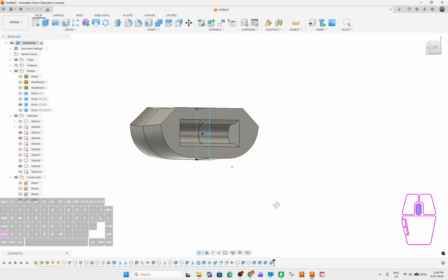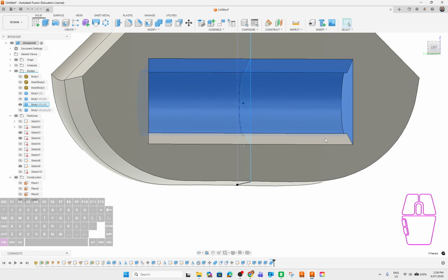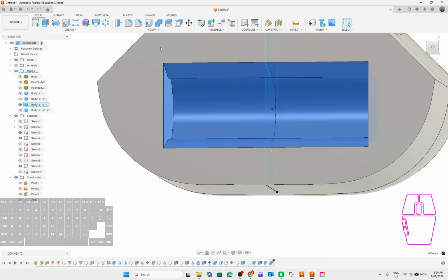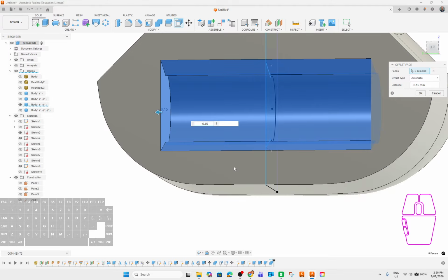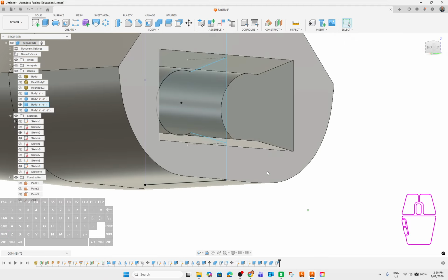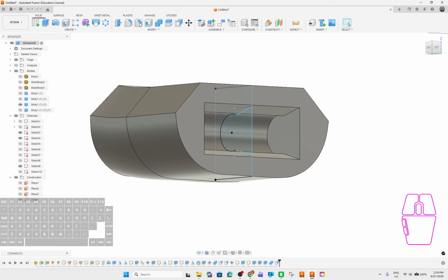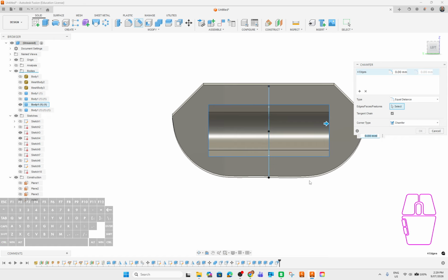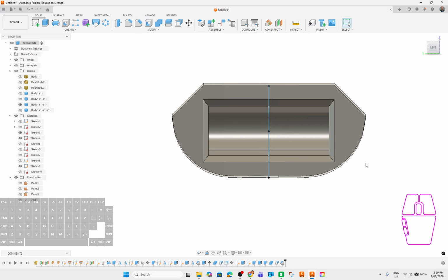Go in here and give a little bit of space to the negative areas. So go here, here, holding down control as you can see while I do this. Then I'll press pull, negative 0.15 maybe, something like that. I don't know. See how that works. Then what else? Maybe some chamfers around here, and on the other side as well, so it just fits in a little bit better. One's way too big, 0.5 chamfer should be good. Cool, so that'll fit in there.